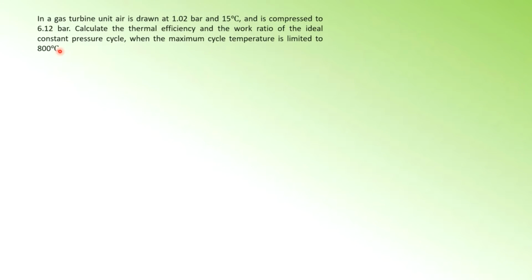So basically, when I solve questions on gas cycles, usually I put it in table form. Okay, so it is easier for you to manage. Okay, and then your work later on will not be so messy and complicated. So that is why I teach you using the tabular method. That means put all the data into a table. Let's say for example, point 1: what pressure, what volume, temperature, and then point 2, 3, and 4 like that.